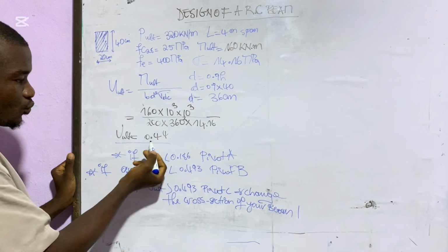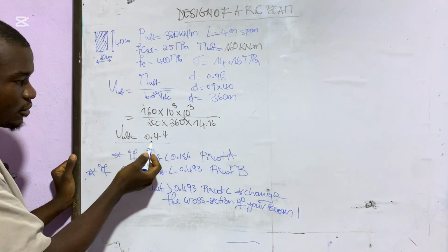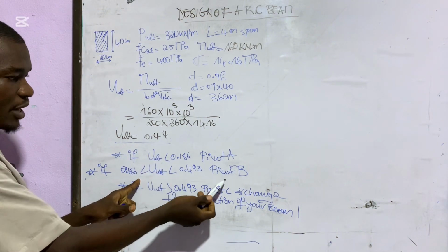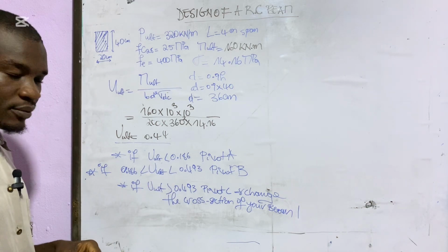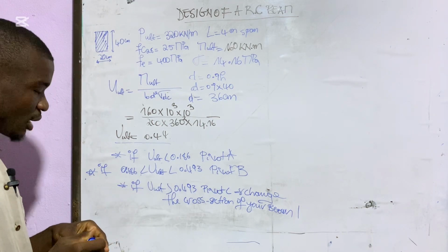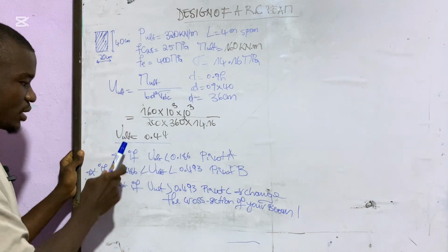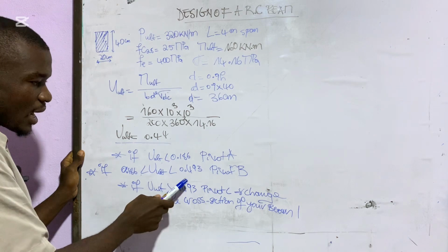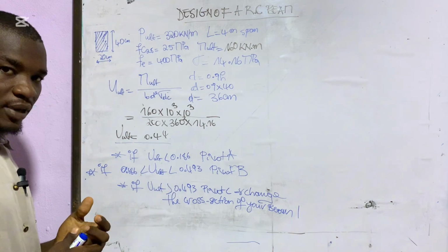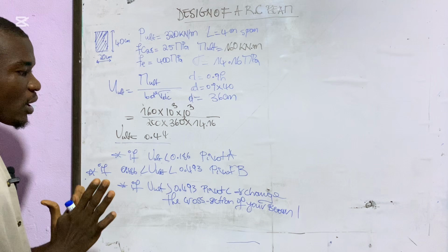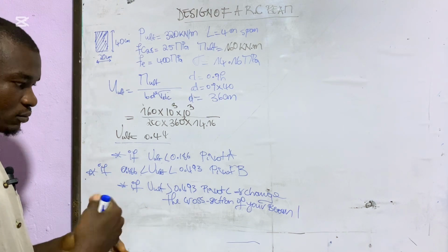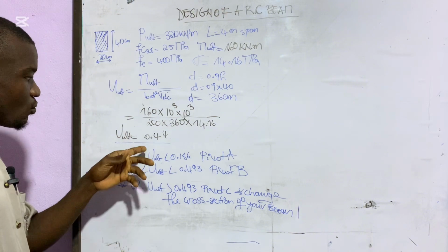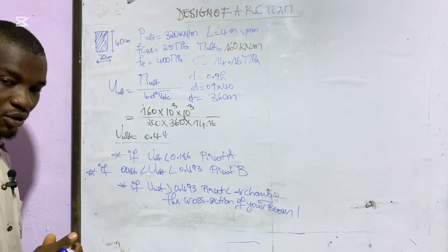Now we are looking at our mu ultimate here, which is 0.44. So we are in the second scenario, we are in pivot B, since our mu ultimate is greater than 0.186 and less than 0.493. This is where we will stop for this first part, and in the next part of the design of the concrete beam, we'll continue with the design of our beam.